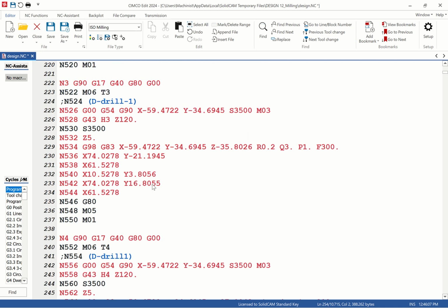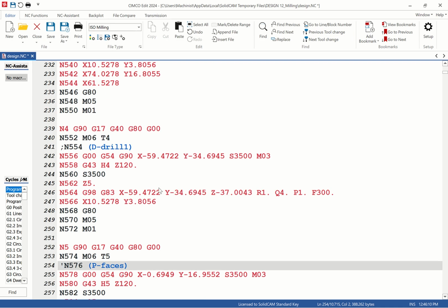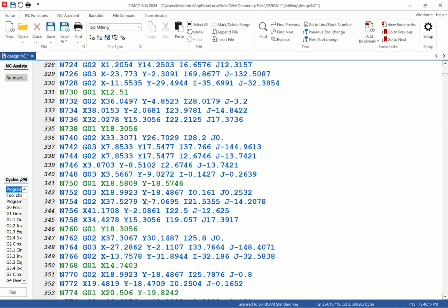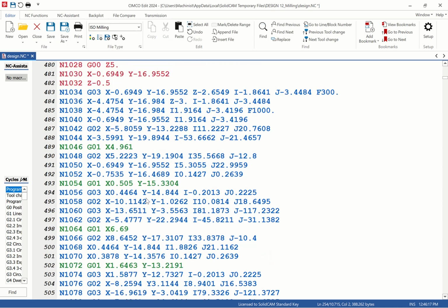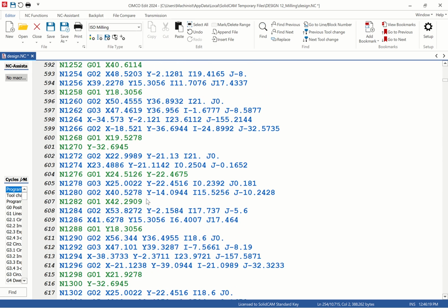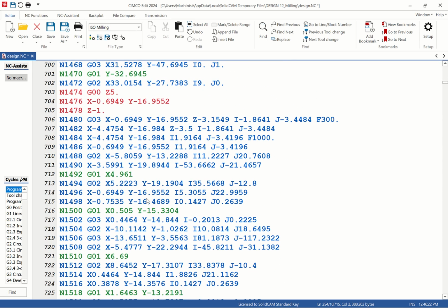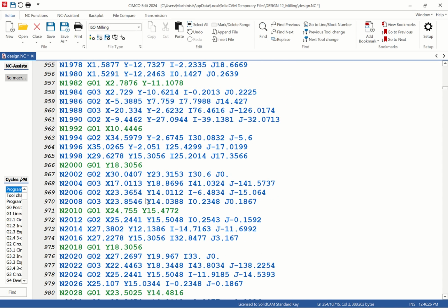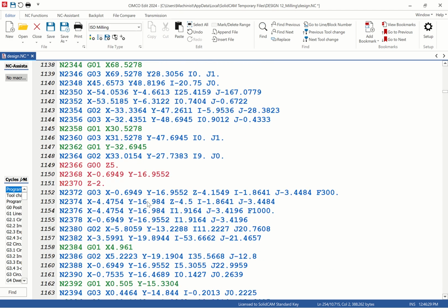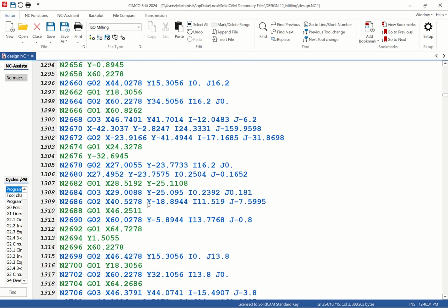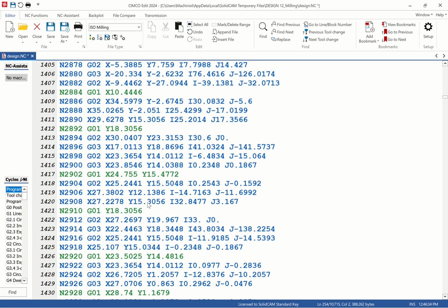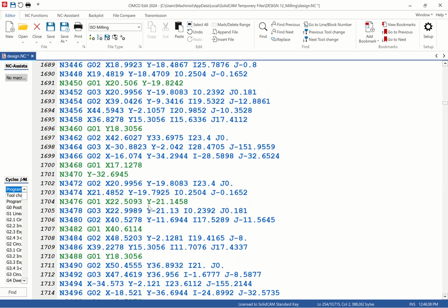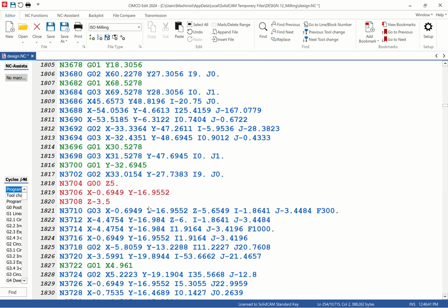Should be using G84. We have that, drill 1, drill 2, pocket, I think arrangement of the program. We'll see. Let me see. Because that's what I wanted to check for this case. Tapping program. Let's go down. That's big. Maybe I'll check if I've done tapping or not. I'll generate again for tapping. Maybe I didn't select for tapping, but it should be there. And that's the program I wanted to check the code for tapping. Okay.